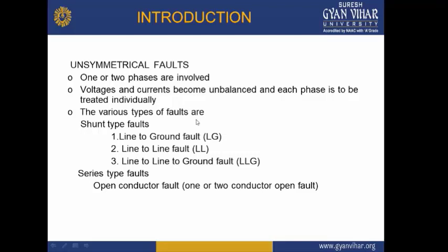Like in a three-phase fault or a balanced fault, we can consider a single phase circuit for the analysis of all three phases, for analysis of the complete network. But we cannot do this in a similar manner for unbalanced faults. Now, the asymmetrical faults are categorized into two categories: first the shunt type faults and second the series type faults.